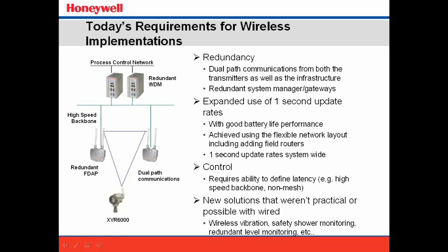I mean, everybody's doing it. They're having to put in 2 independent tank level monitoring systems. The current one's wired. That's great. The wireless one provides not only a secondary measurement, but also a completely secondary or separate communication path. So you're getting more or less 2 levels of redundancy out of that second device. You're not wiring it, running it through the same cable tray, so in the event of a physical problem in that cable tray, you're not losing both level indicators.